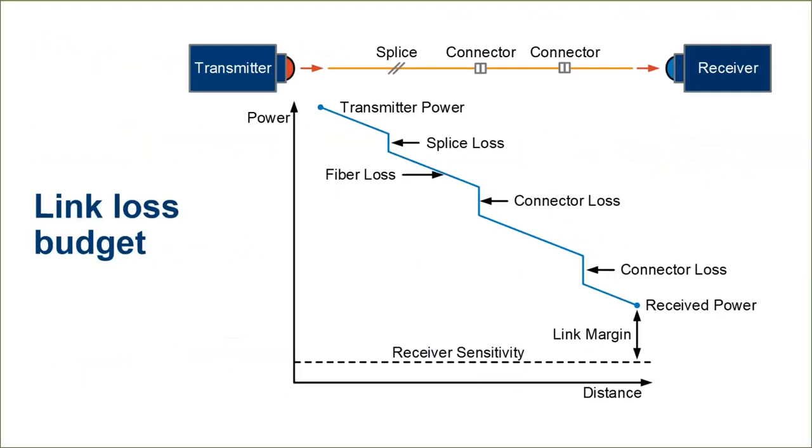A couple of things to take into consideration when designing a fiber optic system is all the losses of the fiber path that should be considered in weighing against the available transmitter power and receiver sensitivity. Additional equipment may be necessary if the loss is too great. Before any installation, I always recommend an optical power budget should be calculated.